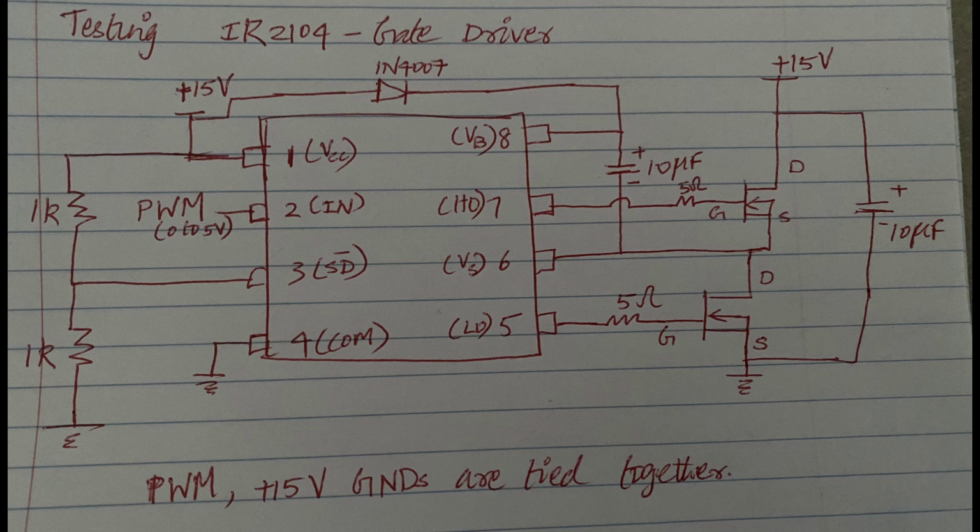Let's build a gate driver test setup to implement this in the real world. I'm using a half-bridge gate driver for this video to show how to control both the high side and a low side power MOSFET. I've chosen part number IR2104. The pin connections are shown here. Pause the video if you need to fully understand how the components are connected.